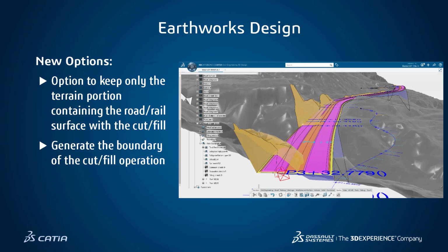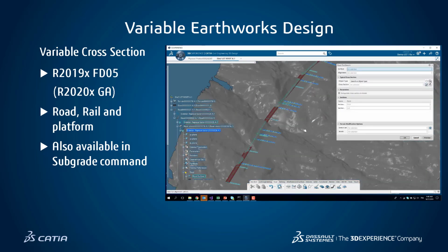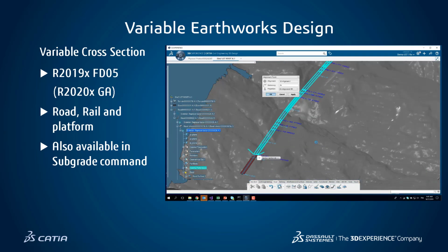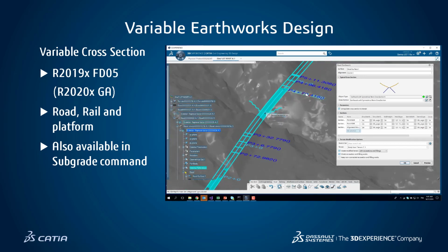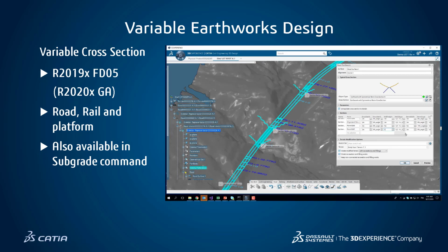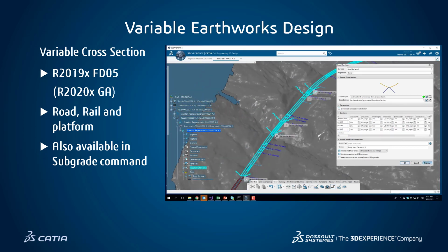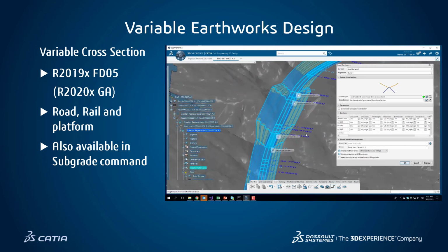can have variable dimensions, and they in one shot can do the Earthworks modifications or Earthworks excavations or filling in the same operation. The variable Earthworks aspect here is when you load the section templates into your model. Here you see the dialog box. You have access to all of those different parameters. You change the parameters, and then they will update on the fly and interpolate between the sections.